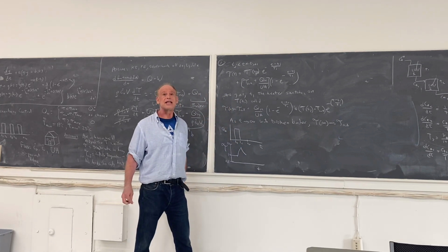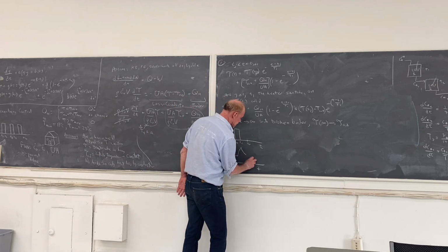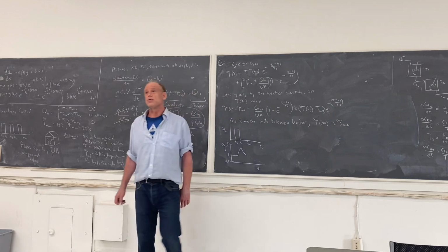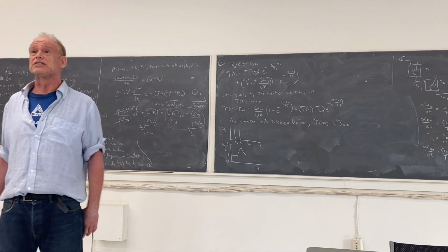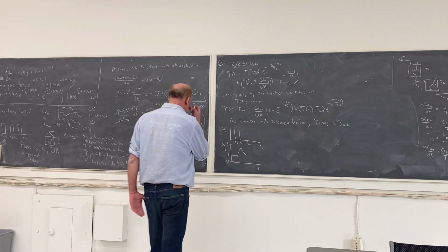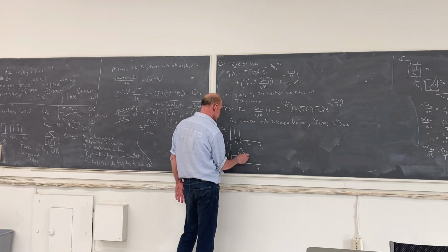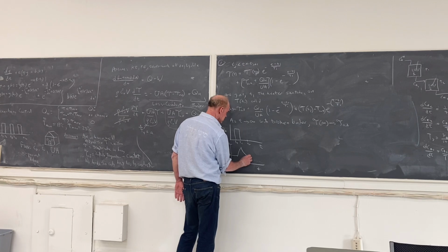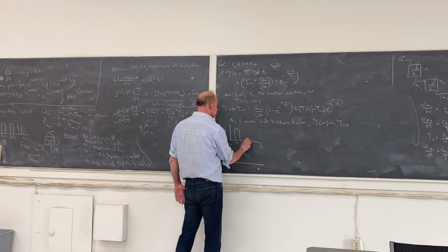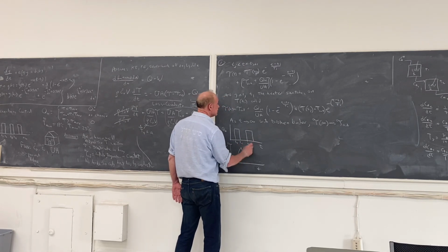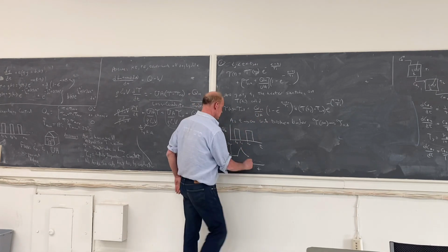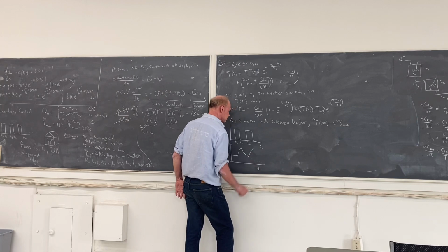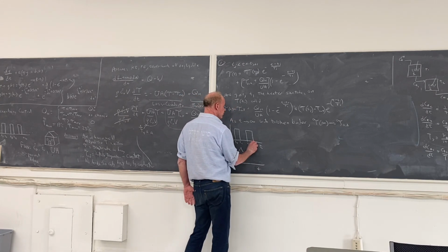And if I let it go, this exponential decay, if the heater were broken, would go down to T out. But I don't want to do that. I don't want to sit in the house till it's 10 degrees Fahrenheit inside. So I turn the heater back on. So at T3, the heater goes back on. And now I go the same solution, but now QH is QH star. So it goes back up. T4.